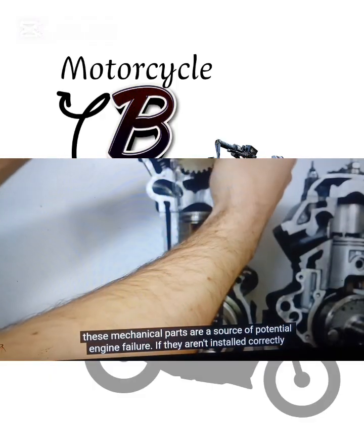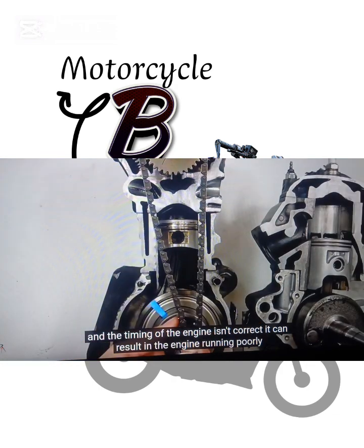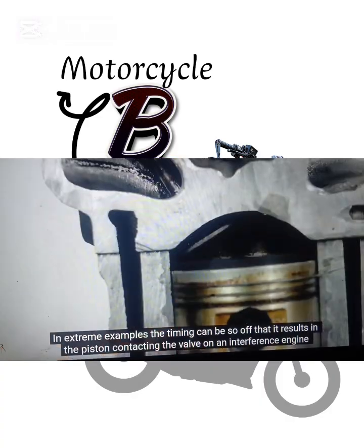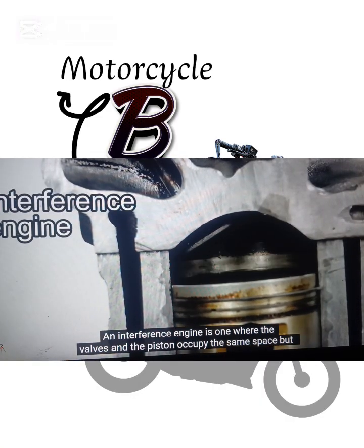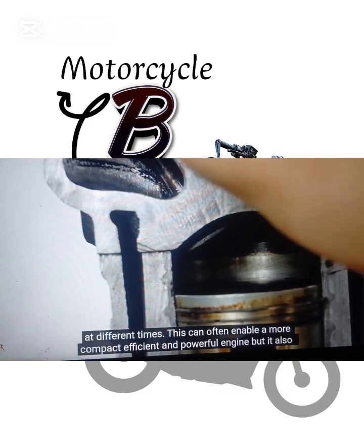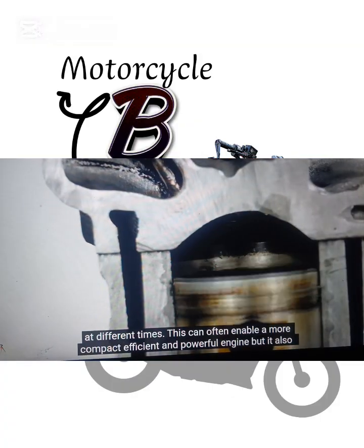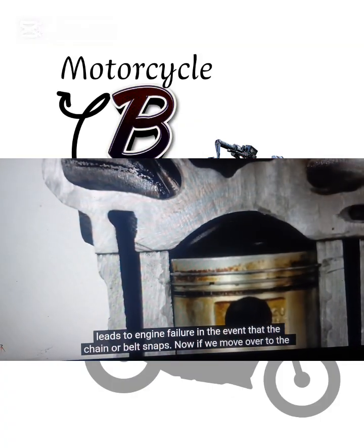If they aren't installed correctly and the timing of the engine isn't correct, it can result in the engine running poorly. In extreme examples, the timing can be so off that it results in the piston contacting the valve on an interference engine. An interference engine is one where the valves and the piston occupy the same space, but at different times. This can often enable a more compact, efficient, and powerful engine, but it also leads to engine failure in the event that the chain or belt snaps.